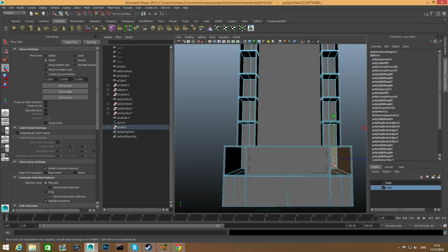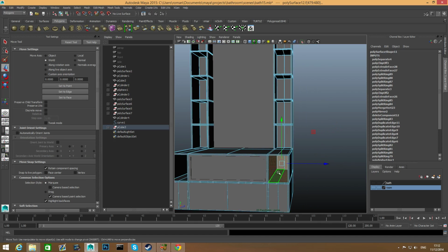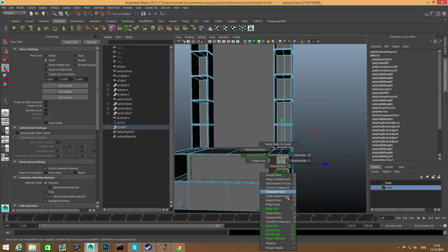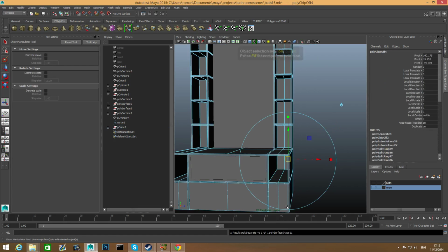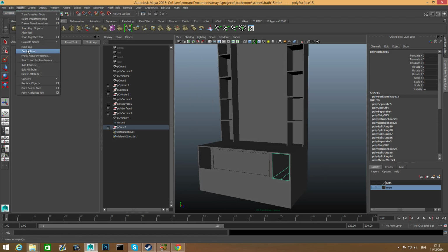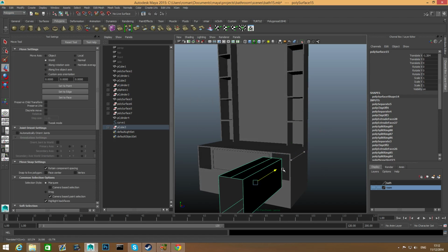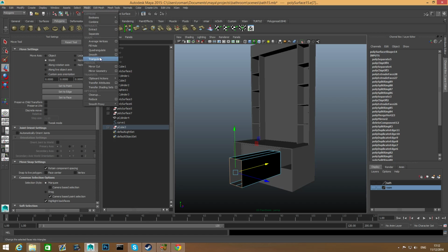And I want to create this one and then copy it over here, but I'm not sure what will happen there. So let's try. Let's just duplicate those. Press F8 3 times. Control to unselect this. Modify, center the pivot for that piece. Let's move it outside. Right click, choose edge. Let's grab this edge. Mesh, fill hole.